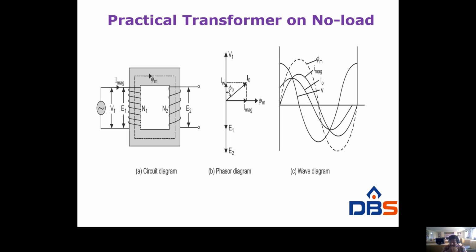That is nothing but the magnetizing current is in phase with flux. Flux and magnetizing current both are in the same phase. That's why I am putting Im here. Now the working component or core loss component is always in phase with terminal voltage. Now the phasor sum or vector sum of the magnetizing component of current and the working component of current is nothing but the no load current. Look at the figure. Now the angle between terminal voltage and I0 is nothing but the no load phase angle phi naught.